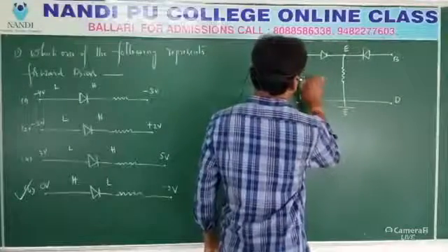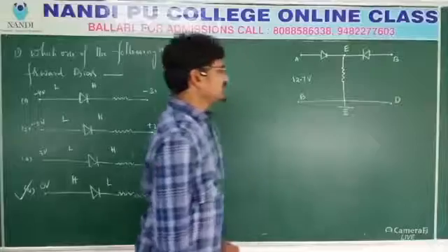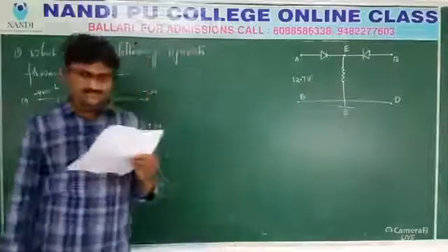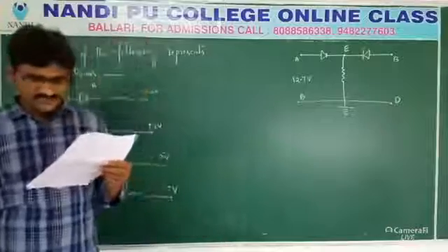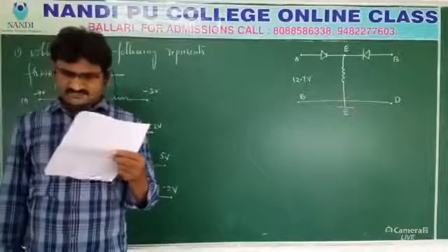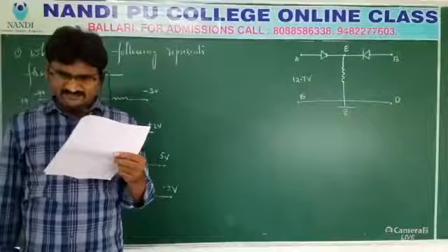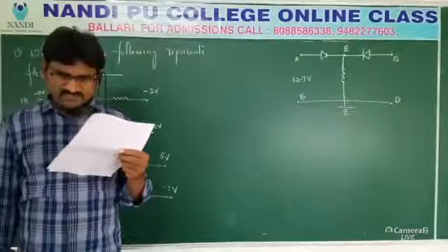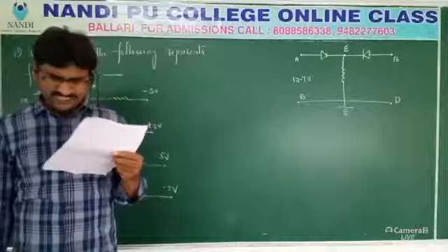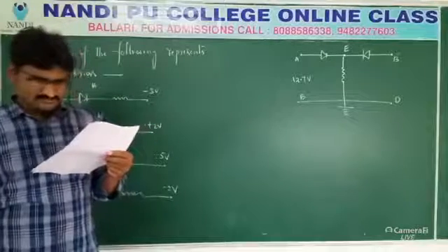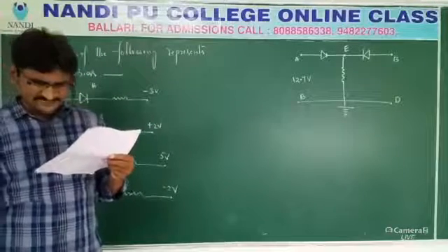You can observe the circuit at A and B, the input is 12.7. Potential in each diode is 0.7. Then what is the voltage at point E?